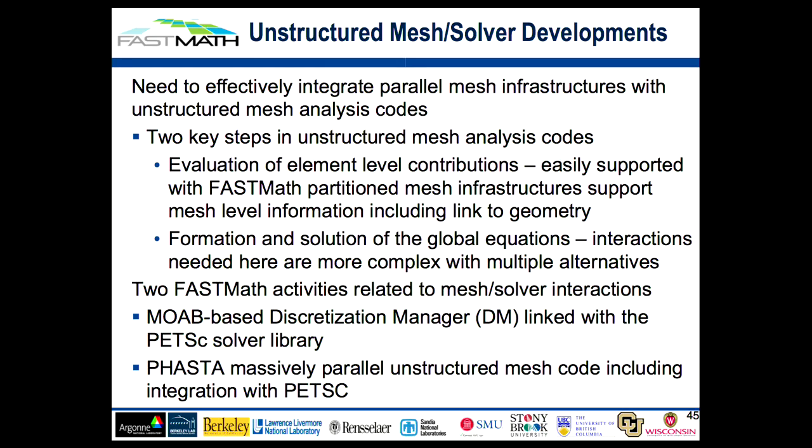Okay, so with those core sets of tools, we want to start being able to integrate those with the solvers. So we need to efficiently integrate the infrastructure with unstructured analysis codes. And the key steps there, of course, are the element formation and then the solution of the system resulting from the element formations and assembly process. And there's 2 sets of specific activities there. VJ will first describe the discretization manager being developed for MOAB, and I'll talk about some work that was done by Ken Jansen with PETSc and the PHASTA code.